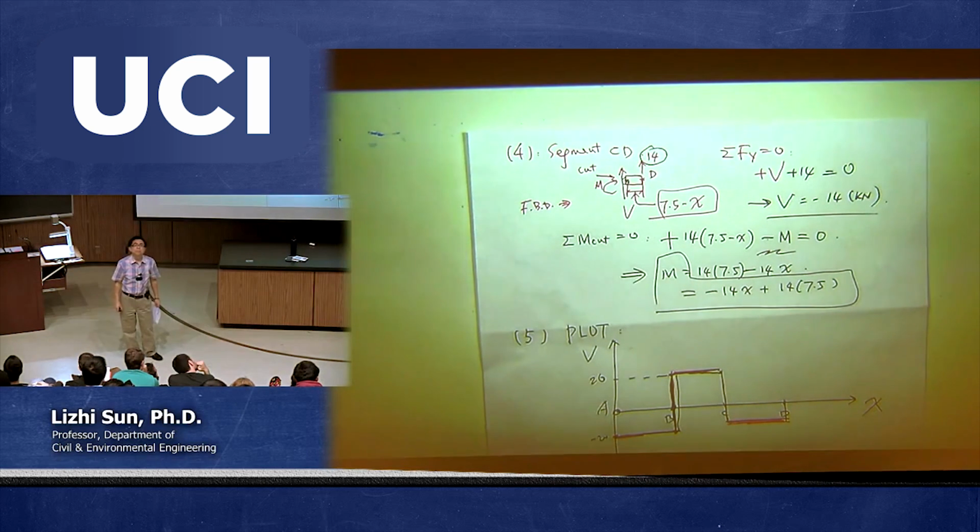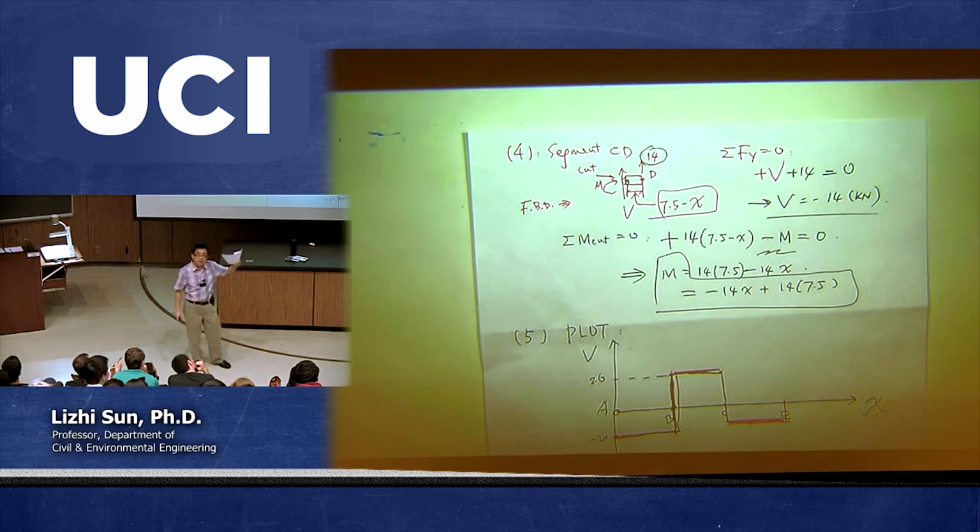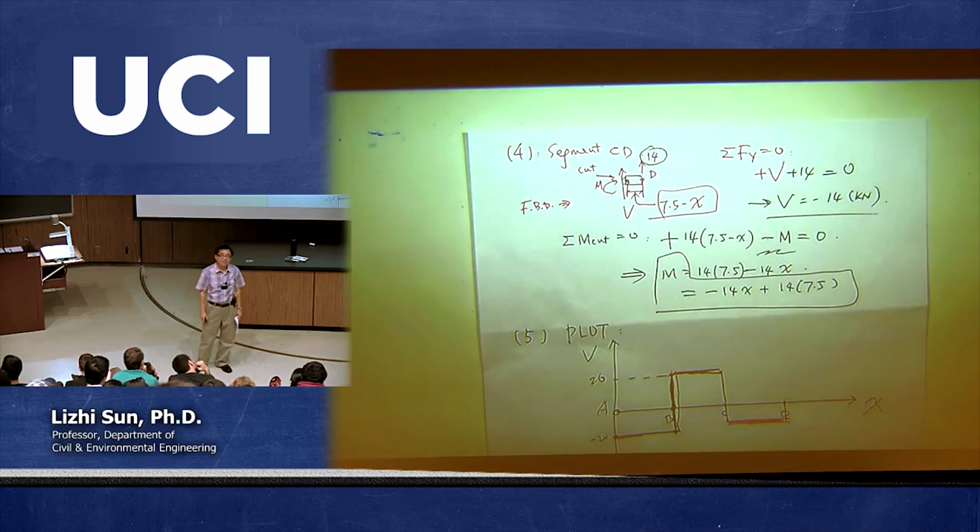Sorry, so when I did it using the left side, I got that the shearing force is positive. Well, when you look at the left side, by definition, by default, did you put the shear force going down? No, I put it up. Then that's wrong. By definition, you need to put the shear force going down if you look at the left side.